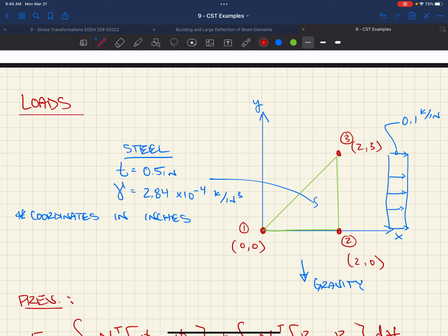You might not have an energy equivalent moment if the loading was such that it didn't have a moment. If you had a series of, say, 10 of these triangles, and we flipped this one this way, copied it up, and ran a uniform load over the whole length, symmetry would tell you that the loading attached to something here, with uniform load equal on both sides, is not gonna want to rotate this node. In that case, the energy equivalent moment on this node is gonna be 0. But on the end nodes, it wouldn't be.